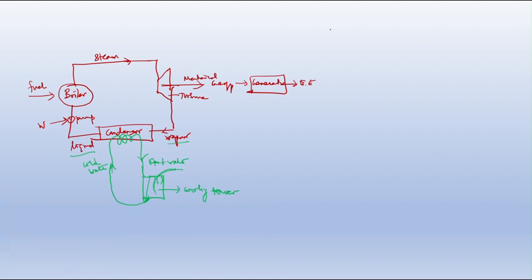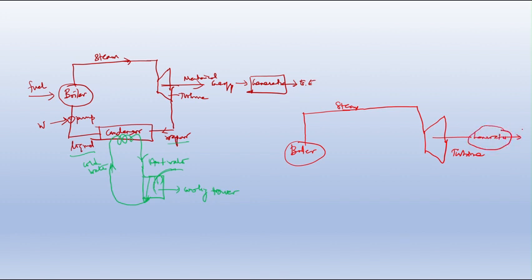The same device, that is a boiler, produces steam. The steam is used to run the turbine, and from the generator we get electrical energy. From the turbine, the waste steam, after the expansion process in the turbine, moves again to the process applications, or some amount of steam is taken out from the turbine. So some portion of steam goes to mechanical power.